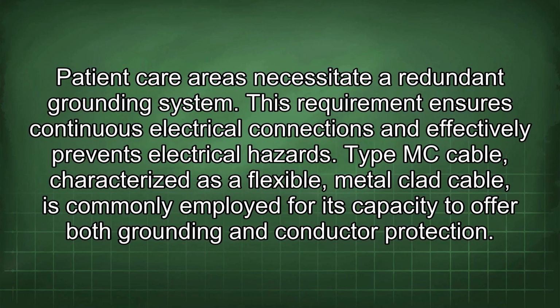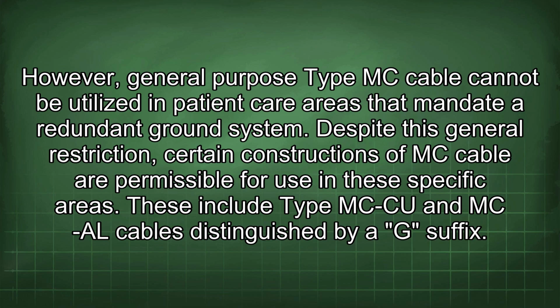Patient care areas necessitate a redundant grounding system. This requirement ensures continuous electrical connections and effectively prevents electrical hazards. Type MC cable, characterized as a flexible metal clad cable, is commonly employed for its capacity to offer both grounding and conductor protection. However, general-purpose Type MC cable cannot be utilized in patient care areas that mandate a redundant ground